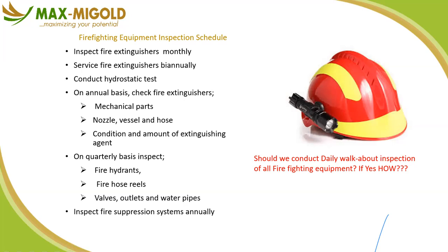And after an extinguisher has been discharged, you need to replace it. When I say replace, I mean you need to service it to refill the gas immediately. Don't say you want to wait for the next round of servicing.